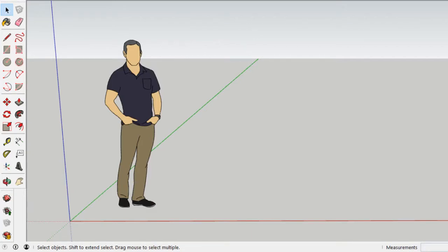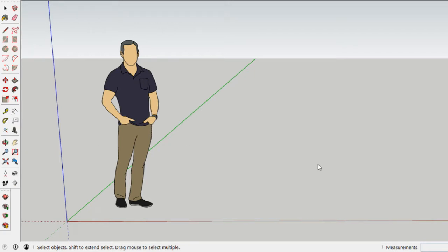And here we are. First of all, let me go back a few seconds. I forgot about these tool buttons. When you first start SketchUp, these tool buttons are big, like this one, and I don't like that, because you don't get every tool. So on the top menu, which you don't see now, we have view, and on the top there is toolbars, and then under toolbars and options we have large icons. Just uncheck large icons, and everything looks better.